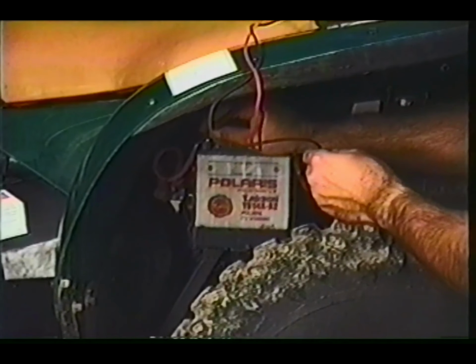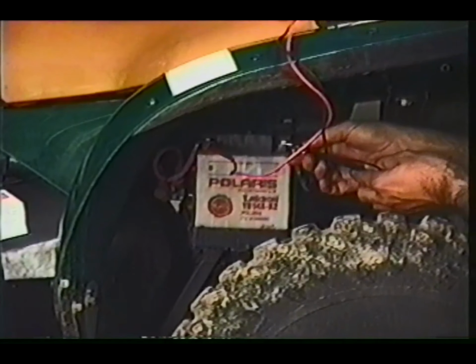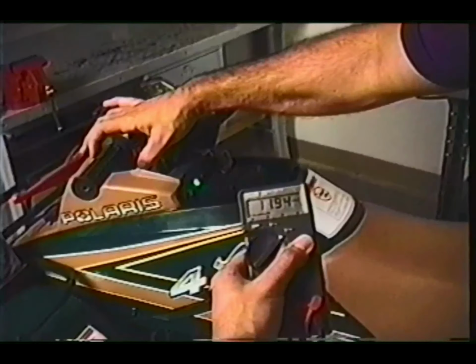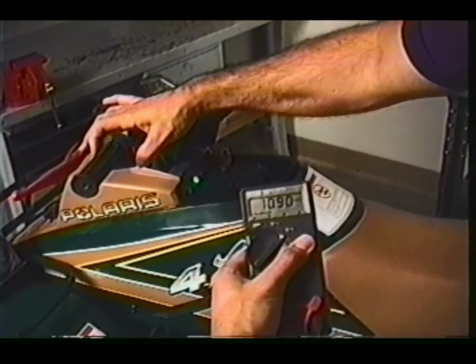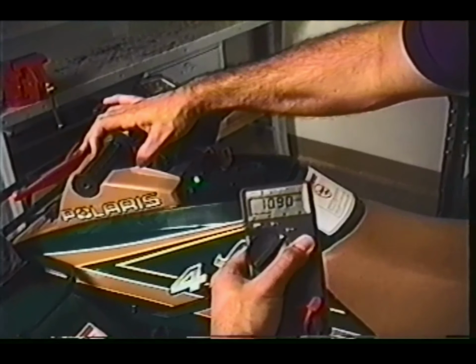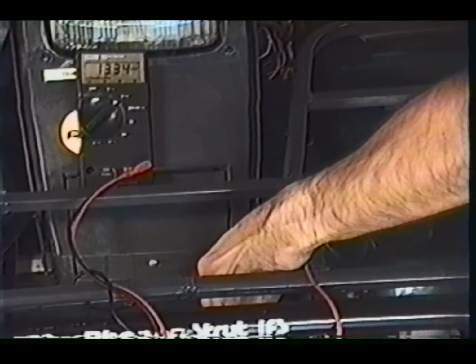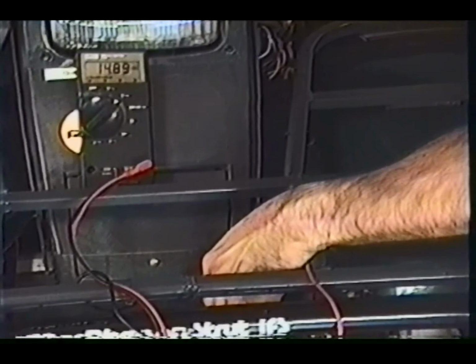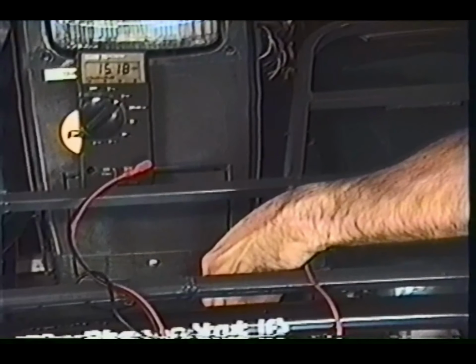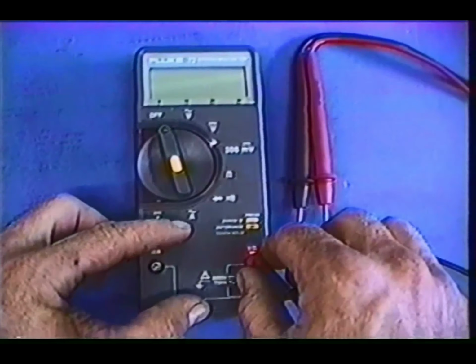In some cases, a battery may show a fully charged state and not function properly. The following load test can be used to test the condition of the battery. Connect the DC voltmeter to the battery as described earlier, and with the kill switch off, engage the starter for 15 seconds. Battery voltage should never fall below 9.5 volts. If the battery was discharged, we need to find out why. A quick test of the charging system is to start and measure the DC voltage at the battery. Connect the DC voltmeter, start the engine, and increase the RPMs. Battery voltage should increase to about 14.5 volts.